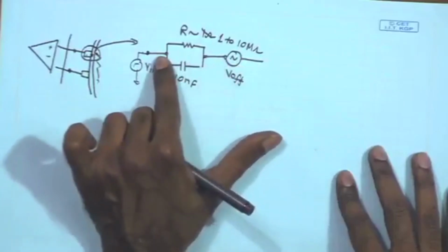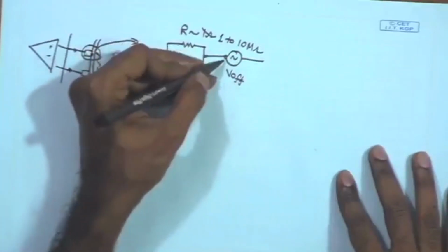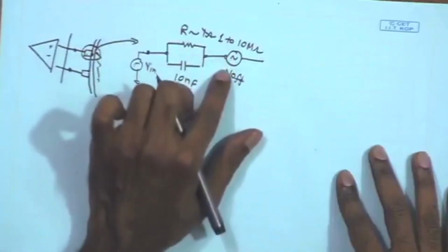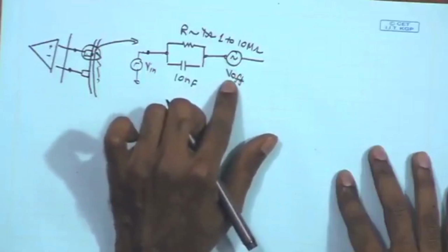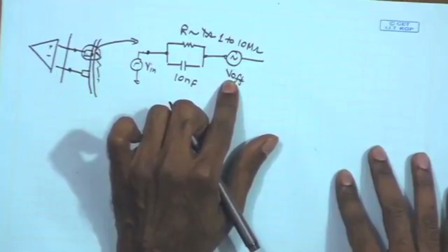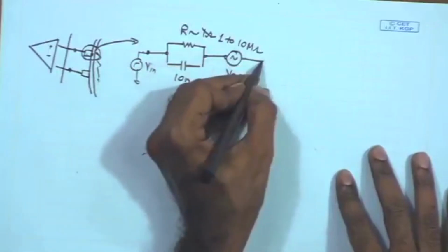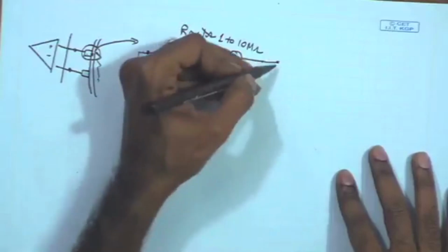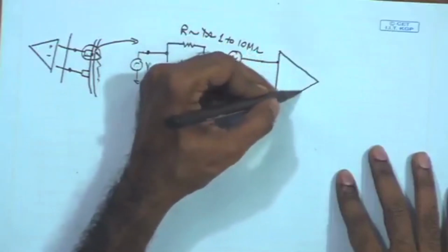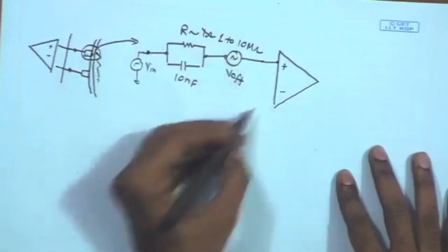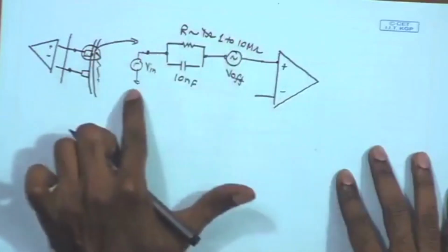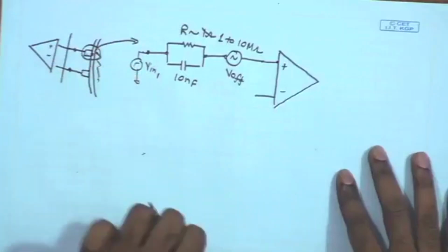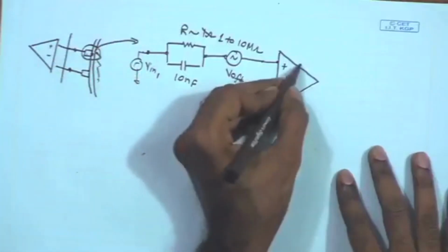electrodes with the skin. So, because of the interface defects or because of the artifacts between the electrode and skin contact, there can be an offset voltage created, which is a very slowly varying signal, but it can be very large in magnitude. We will look at the specification of this as well. So, this is the input signal which is going into our differential amplifier. Likewise, you have another channel which is also having a similar electrode model, only thing is it will be having a V into the negative terminal.